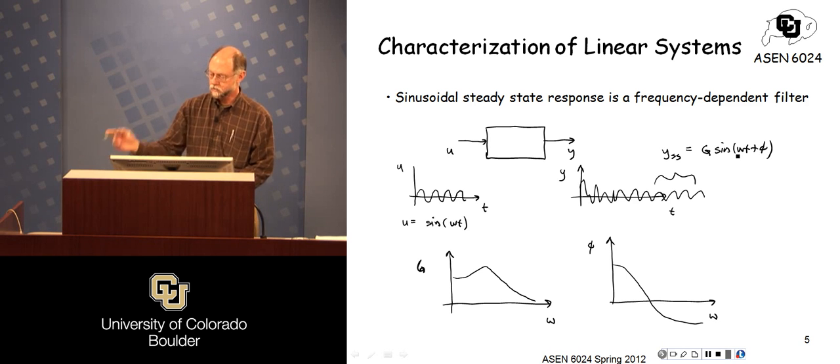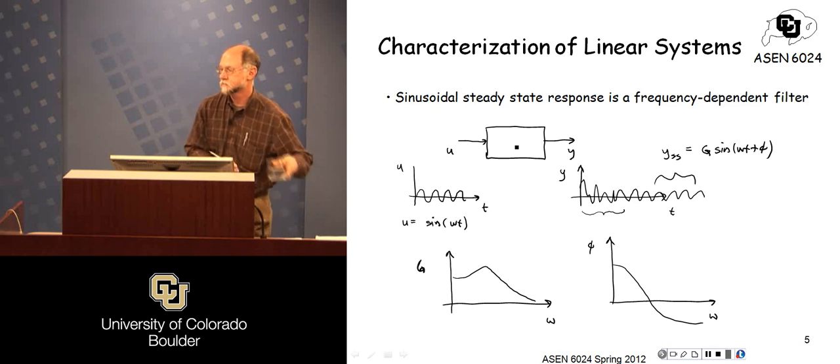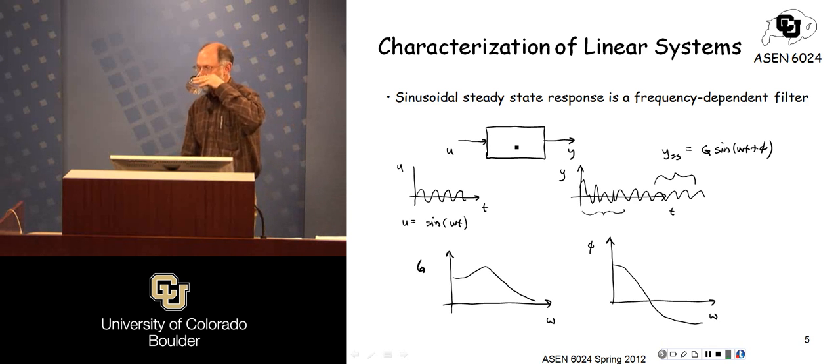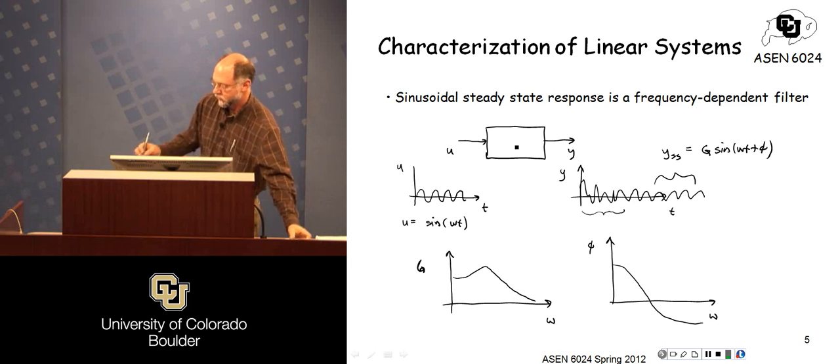The thing to not forget, though, is that we only have the situation where the transients, the natural responses, those e to the at things we just talked about before, only decay to zero under certain conditions on the system. And what are those conditions? All the eigenvalues have negative real parts? Yes, exactly. All the eigenvalues have negative real parts.